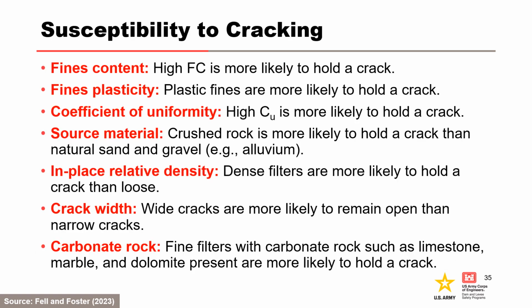Here are some factors influencing whether a filter will hold a crack and whether that crack will remain open. Filters with high fines content, plastic fines, or high coefficients of uniformity are more likely to hold a crack. Crushed rock filters are more likely to hold a crack than those that are manufactured from natural materials. Angular natural gravels may behave in a similar manner to crushed rock, and filters with a mix of both should be considered as crushed rock filters.